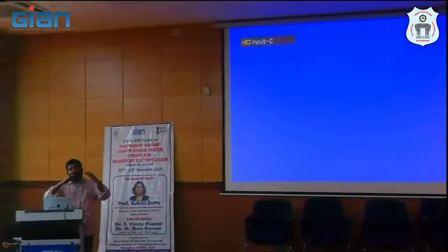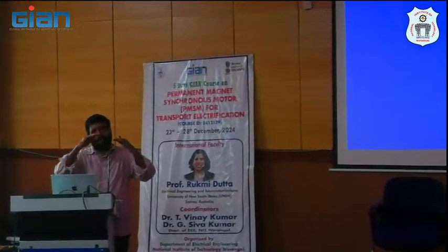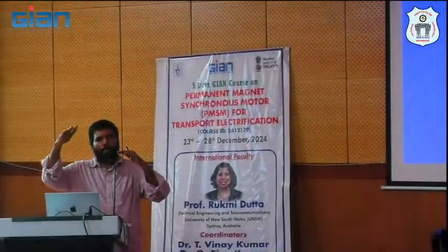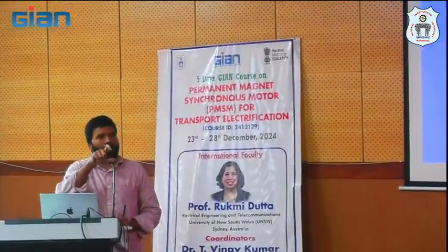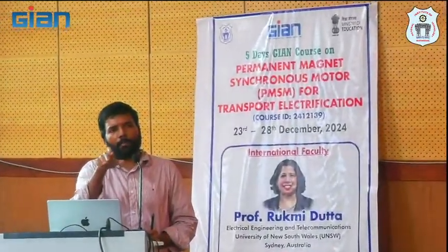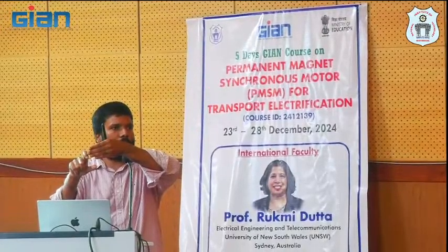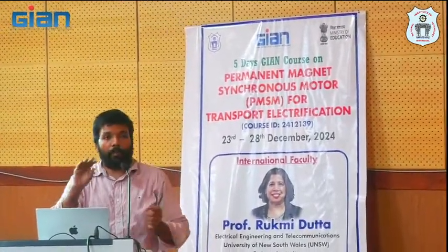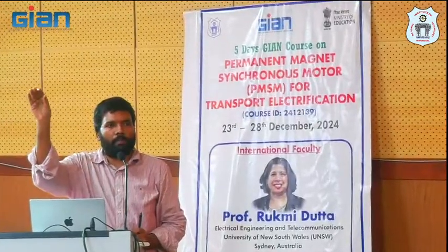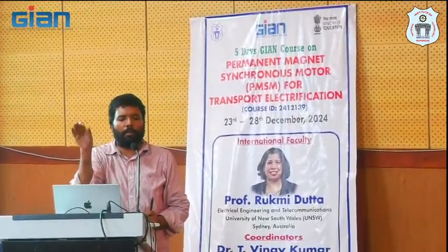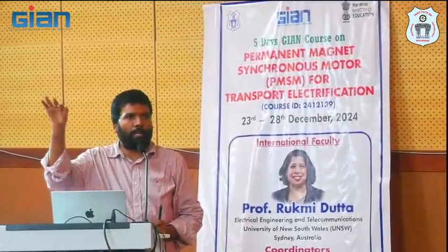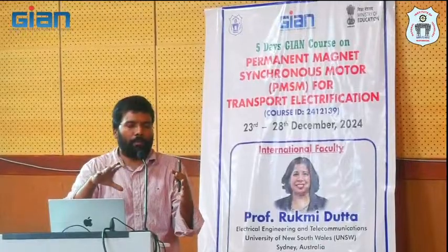Even if initially your requirement is 1000 RPM, they will not give the reference directly. If you give reference 1000 RPM, what will happen? It will be applied to the integrator, and your 1000 RPM will slowly update. Initially only 10% of the reference speed will be released, so your reference speed becomes 100. After some time delay, one more 100 will be added, so 200, then 300, like that. Your reference speed will go in step fashion, increasing cumulatively, even if you give 1000 RPM initially.